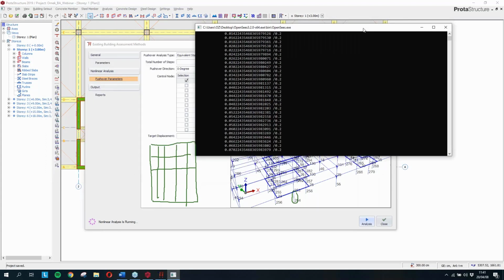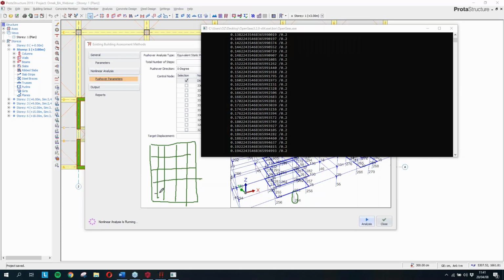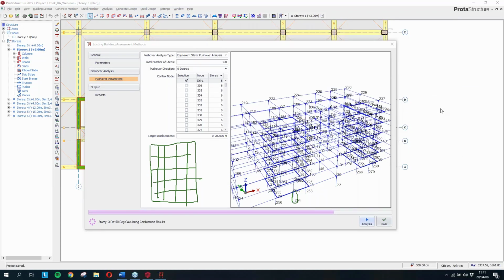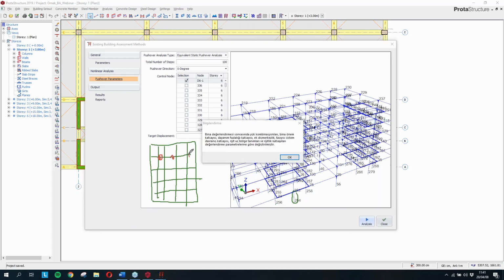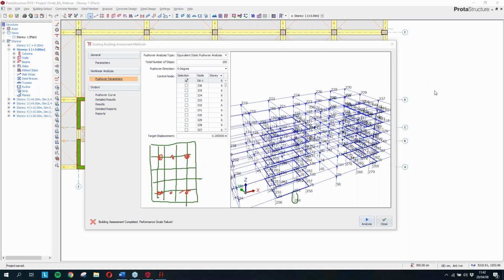Let's just turn the mouse and put it here. And when we prepare our fiber models with all reinforcement fiber locations, we prepare our material models for each of these fibers. After preparing them by using Mander material models, after preparation of those fiber section definitions, nonlinear section definitions, we prepare our force deformation. We export our force deformation relationships as moment curvature relationships.